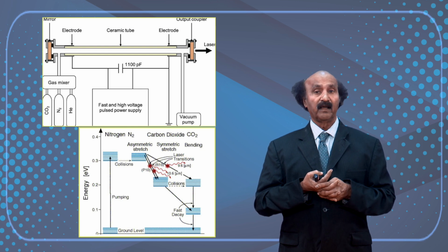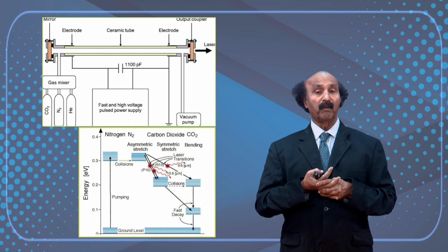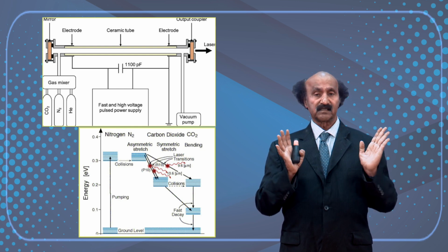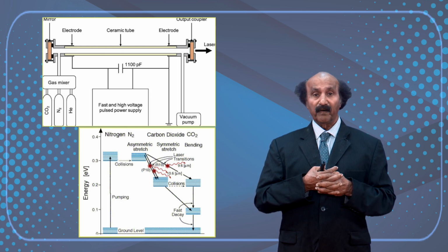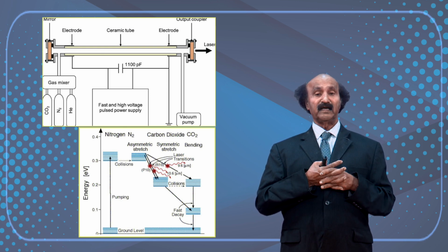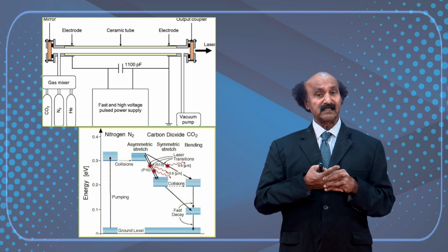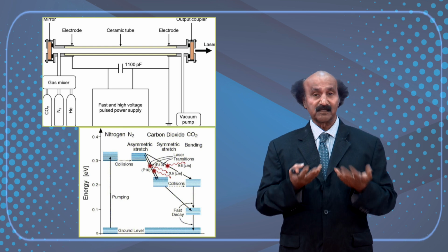On the other hand, if I go to 300 K, that is about 23 degrees C, a typical room temperature. Then you can easily see the power increases, the inversion density easily gets doubled, because the lower energy level will be practically empty. That is the point.